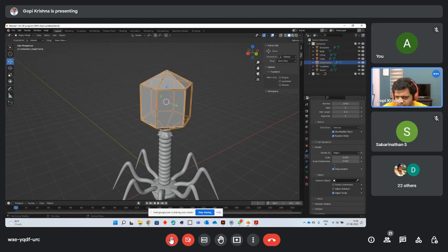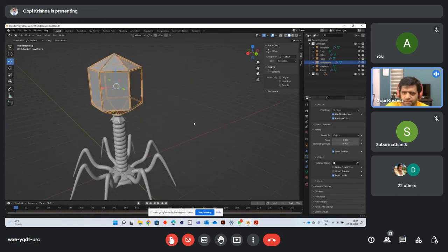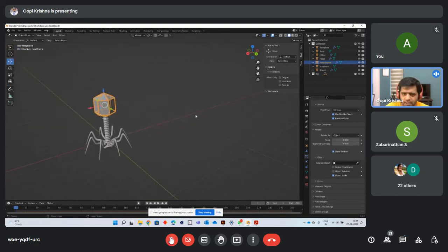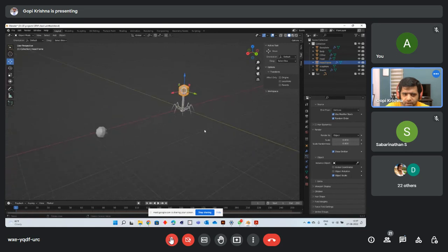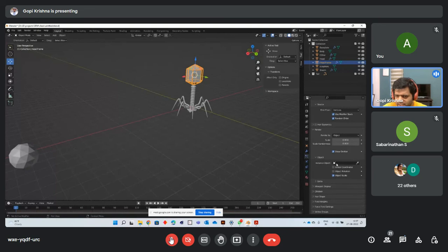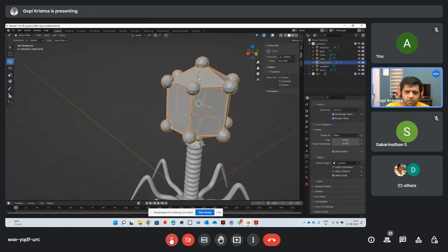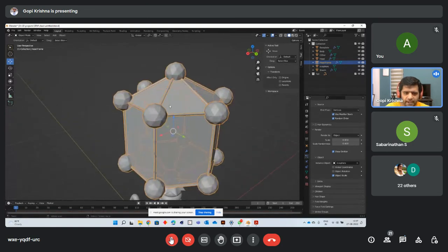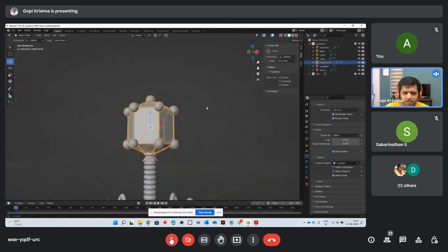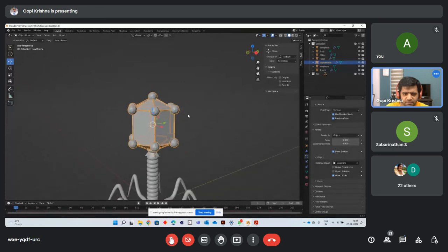The very next line is asking me what object I want it to render as. It's asking me what the instance of it is. So I click on this eyedropper, come here, and select this icosphere. See, now you have one icosphere on individual vertices.